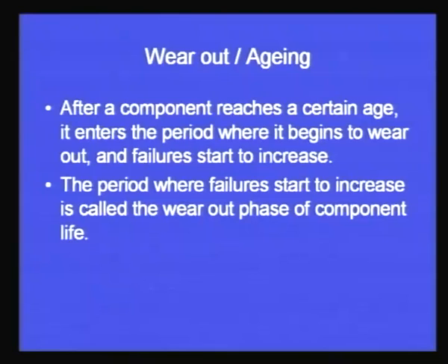Finally, the third phase is the wear out or the aging. So, after a component reaches a certain age, it enters the period where it begins to wear out and failures start to increase. So, after the normal life is over in the bathtub curve, the wearing out or the aging phase starts, in which the failure rate again increases.